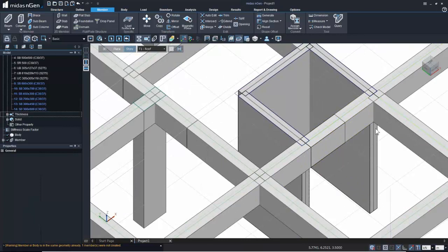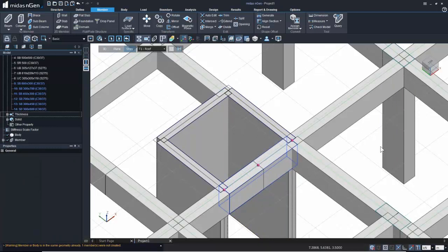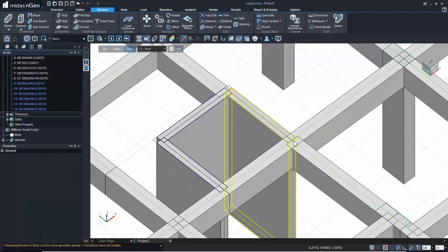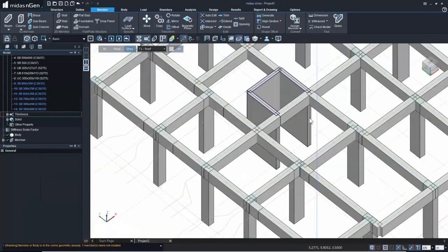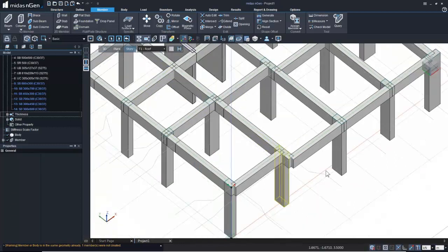These elements are actually divided, so I can even ask them to merge these beams together. Alright, so this is done. There was one line element detected over here, and there was one line element completely running from this location to here. So I deleted a half portion of it, and we are done with our beam modeling.